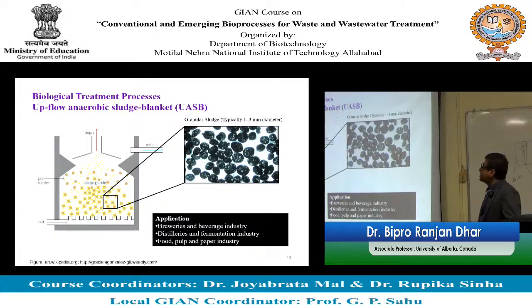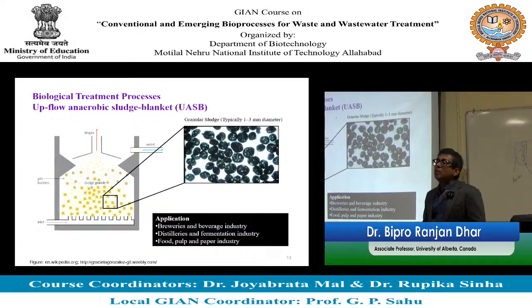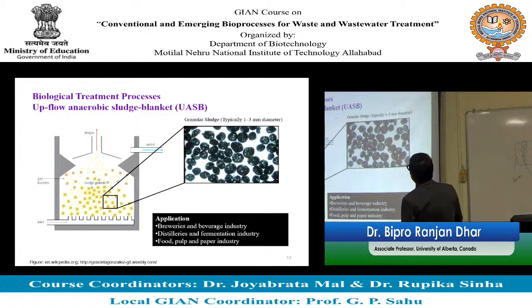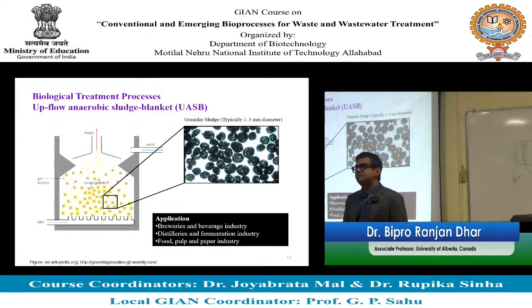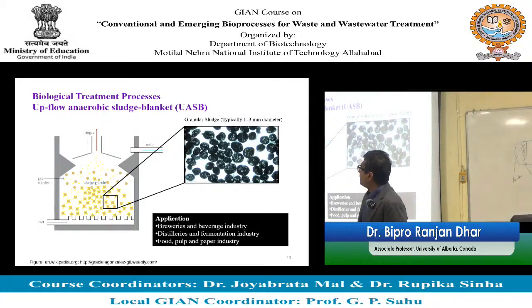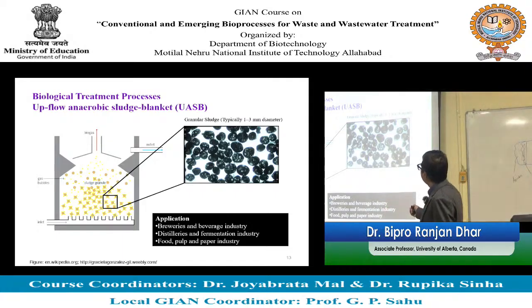And the unique feature of this design is that the microbes are still in suspension, but they are going to be in granular form. You can see this microscopic image. What is the size of microbes, any idea? They are in the micrometer range, right? That's why you call them microbes. But you see those granules can be 1 to 3 millimeter in diameter.